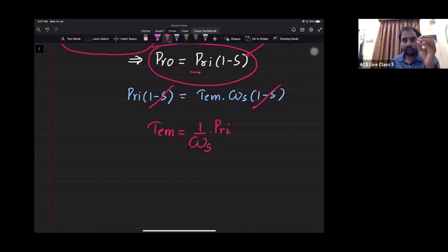Till now, I was trying to tell one thing. If the rotor circuit is highly inductive, the active power drawn will be less. The torque which depends on that will be less. So that is the reason yesterday I took some time to explain why the starting torque is less. At starting, the rotor frequency is equal to the supply frequency. So the inductive nature of the rotor circuit will be more compared to the resistive part. Because of high inductive nature, the rotor power factor will be less.